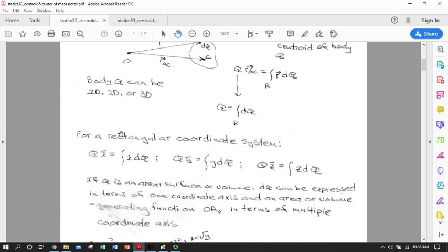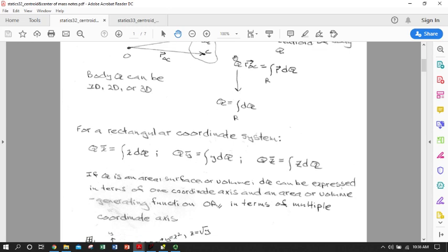Okay, so if we impose a rectangular coordinate system, which we're going to be using most of the time, we can take this general expression here and drop in X, Y, and Z. So again, we've got our total body volume, area, or length, because we could be talking about X, Y, or Z, and then we could define an X centroid, and that would be equal to the integral of the X location, and that's just X referenced to X equals 0, so it's a radius from X equals 0 to X equals some X, dq, which could be a dx, dy, ds for a path length, or a dA if we have a two-dimensional body, or a dv if we have a three-dimensional.